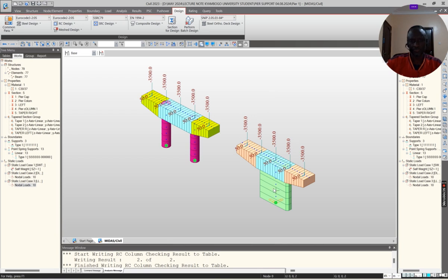I tried to model two similar support systems, a pier column with a pier cap, and then a single pier column, or what they call a pier wall. But a pier wall is when the width exceeds 6 meters, and columns are about 6 meters. You can confirm what qualifies to be a column and what qualifies to be a wall.